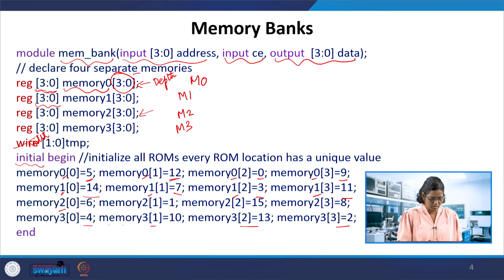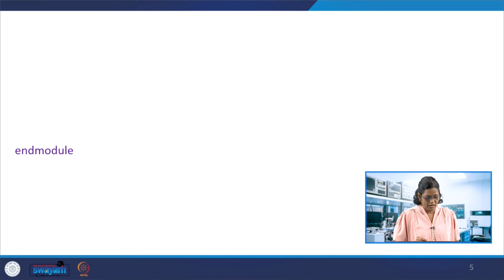Similarly, the size of the memory can be decided according to the data. If you want to store 128 data, then you need to go for this splitting of memory, if it could be split with an equal number of locations, that's fine. Otherwise, you have to use only one memory which can store all the values from 0 to 127, for example. So here I am showing an example wherein you can have smaller memories as well. Now the data is loaded into the memory using this module.